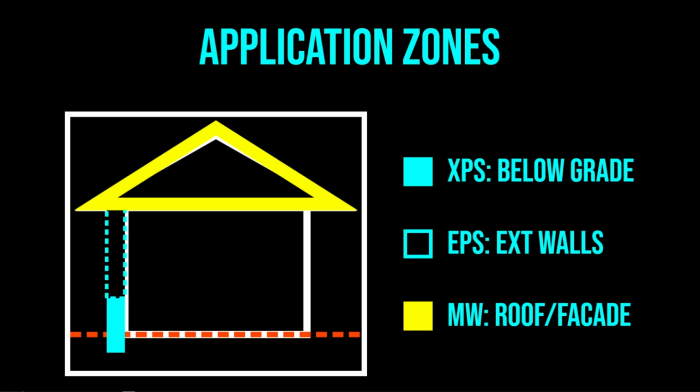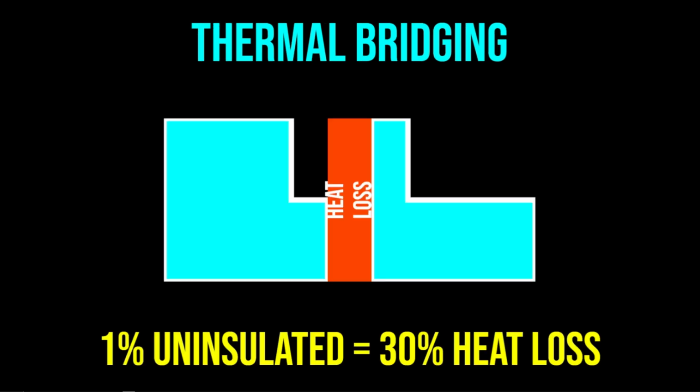In flat roof construction, the choice depends on the buildup. An inverted roof, where the insulation sits above the waterproof membrane, requires the water resistance of XPS. A warm roof buildup, where the membrane is on top, can utilize mineral wool or EPS. Each decision must weigh thermal efficiency against the risk of moisture accumulation, fire spread, and the mechanical requirements of the specific building component. The theoretical performance of insulation is often undermined by poor installation.